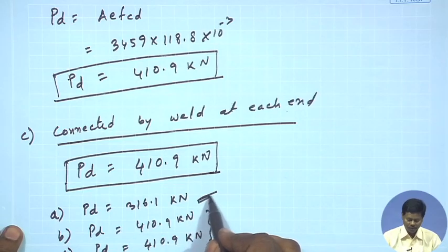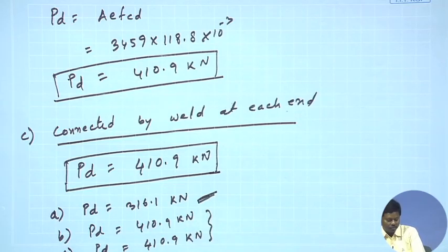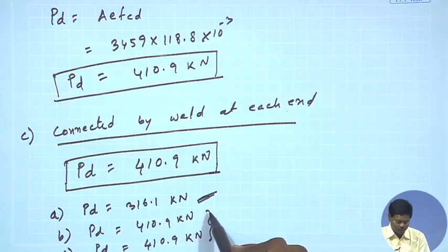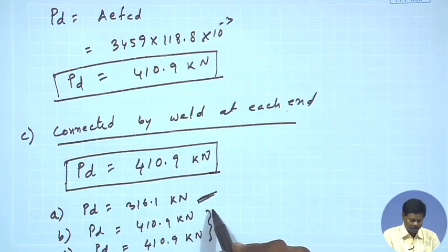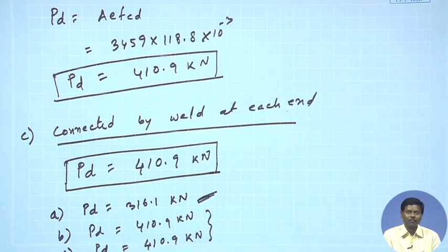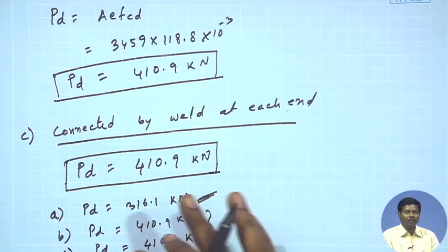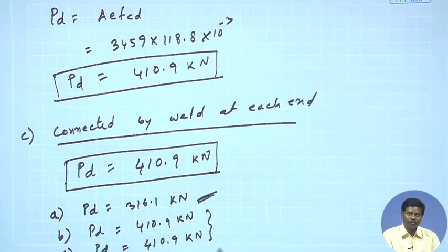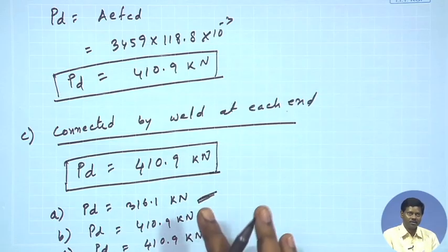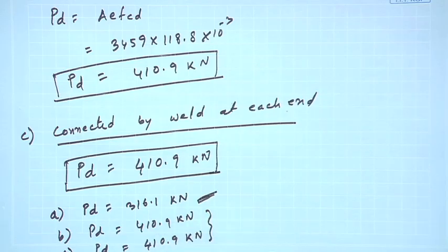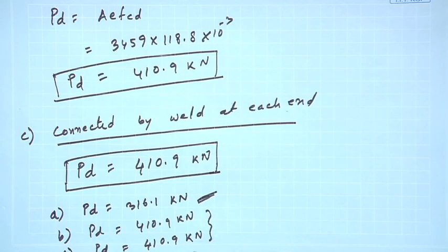So, if we want to increase the strength of the member, we should choose a higher number of bolts, means where 1 bolt is sufficient, we will choose 2 bolts with smaller diameter. So, that we can use 2 bolts as well as we can increase the strength of the member. This is how we can utilize this advantageous thing, and we can allow more load for such type of connections.